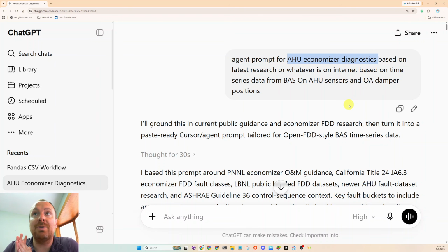In typical retro-commissioning, the really good projects that I've seen in the past would have a peak heating season, a peak economizing season, where you test economizing, mixing dampers, free cooling, sequencing on airside systems, and then also a peak cooling season. So usually three things in a really good retro-commissioning project or data analysis. And we can focus on one of them here because we have a complete shoulder season data set.